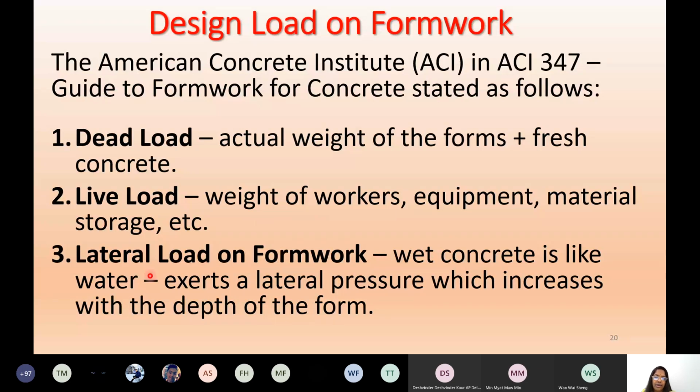Lateral load on formwork. Wet concrete is like water, slurry type, and exerts a lateral pressure which increases with the depth of the form. Because it's mixed with water, and water tends to shear, right?